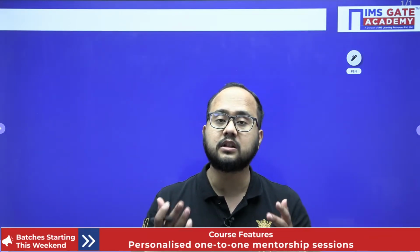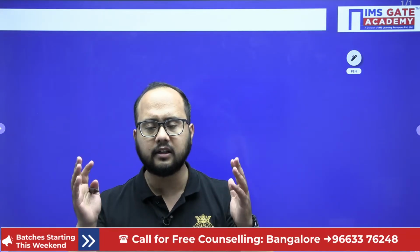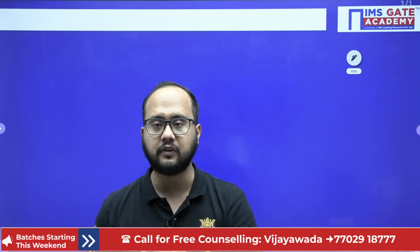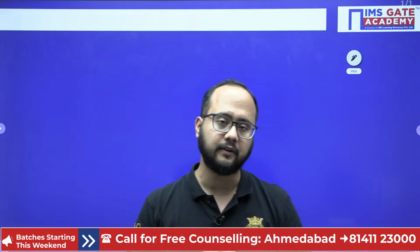Most of the time the common mistake is that students will say, sir, it is conservation of energy. We have discussed it is not simply conservation of energy, it is conservation of mechanical energy, in which we have considered pressure head, kinetic head, and the datum head. The summation of these three heads is constant during the flow in Bernoulli's equation, and we have also seen some assumptions that we have taken while deriving it. I hope all those points are clear to everyone.